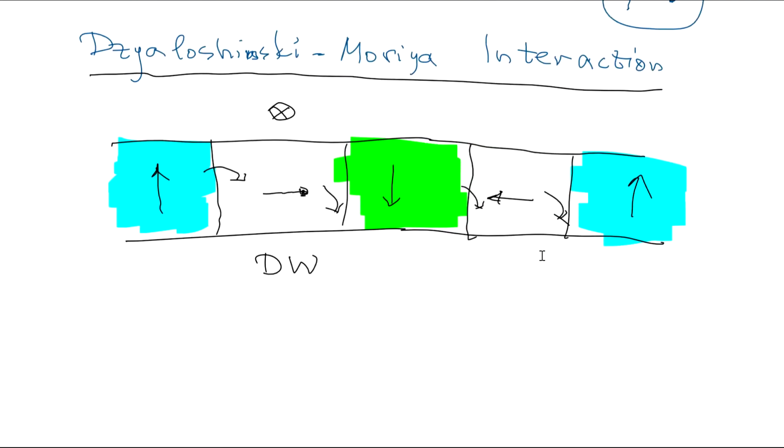So what happens is that we are able to stabilize very small domain structures. If you would make domains less than, let's say, 40 nanometers, they would vanish, they won't be stable. But in these materials, we can stabilize very small domain sizes. Why is it important? Well, if you write down the memory, instead of writing that into 40 nanometers, you can write it into a much smaller structure.